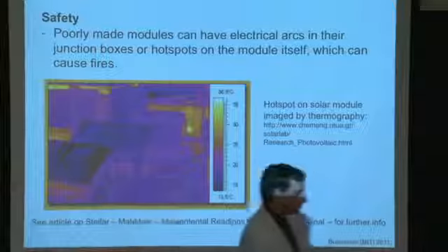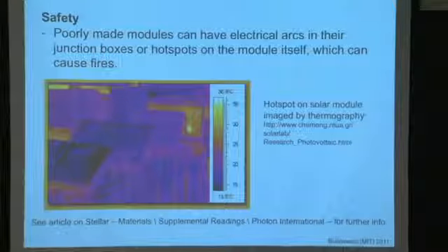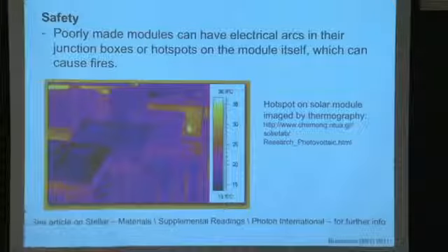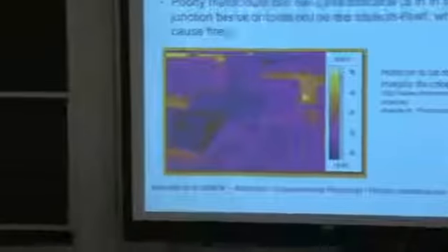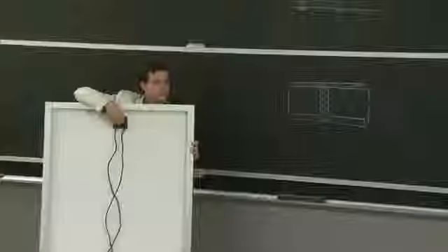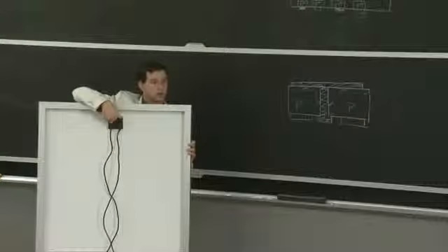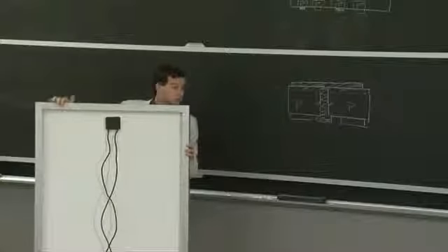And there are as well hot spots or heat that can be generated from the junction box on the back. This contains a fair amount of electronics again, and if there is some failure of the electronics inside of here, you could have the combined power output of the entire module arcing right through a given component back here, causing sparks to fly.